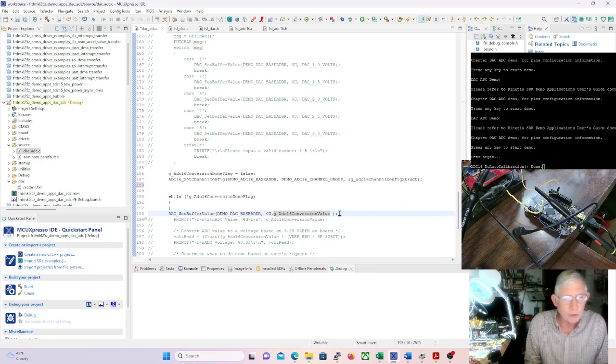Now what we're going to do is take a signal generator, and we're going to make sure we set it so we keep the voltage within the 0 to 3.3 volts. Most times the signal generator is going to have a signal that has its center point at 0, and it's going to go plus or minus.